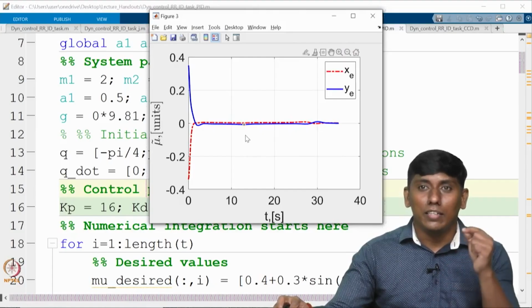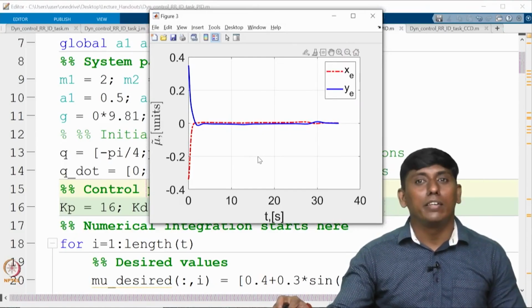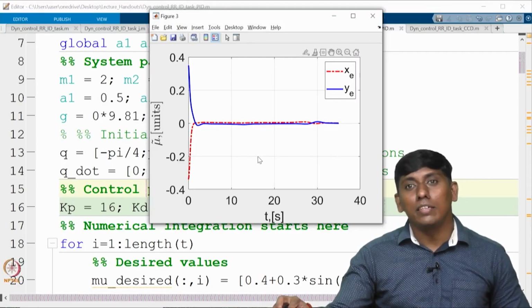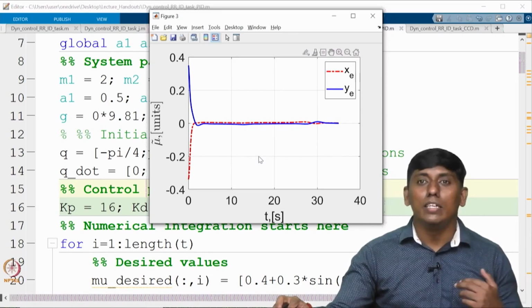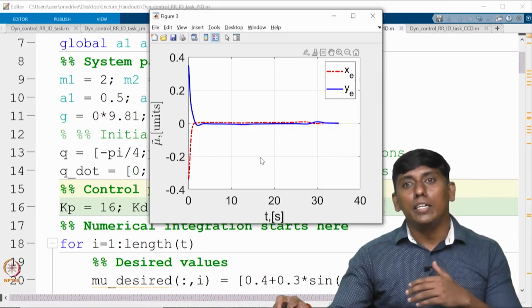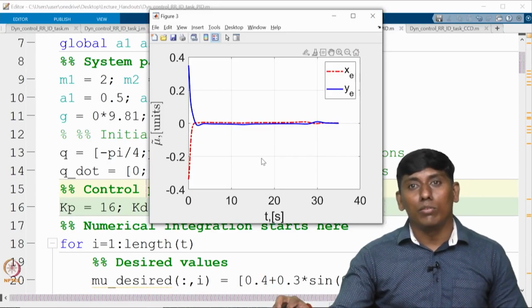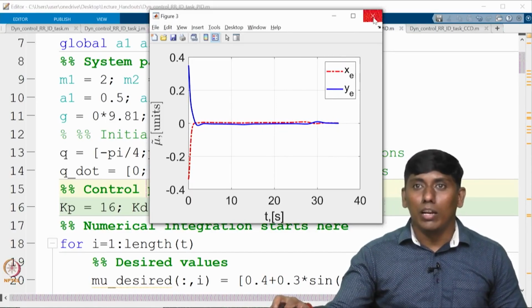Now the integral is actually pushing different regions. So this is what I want to emphasize. The PID control is not preferred most commonly in the robotic manipulator community over the PD, because the I term can end up with what you call wind up. So that's why we can avoid this particular PID control. So now you are clear.